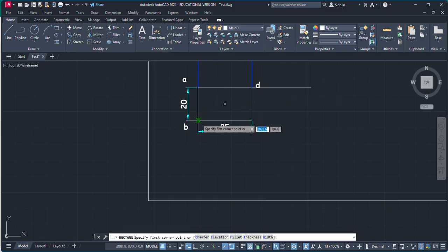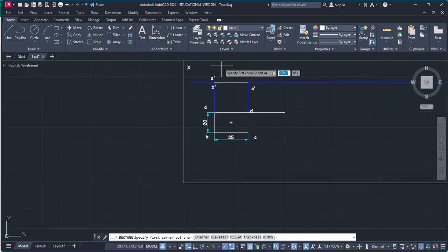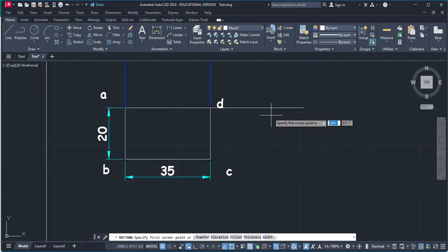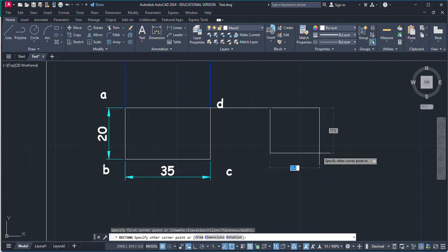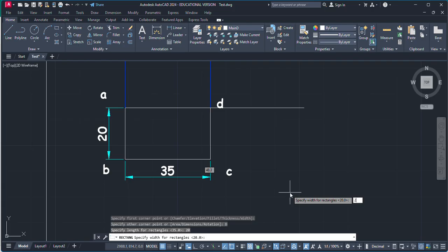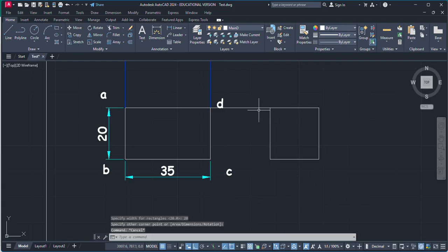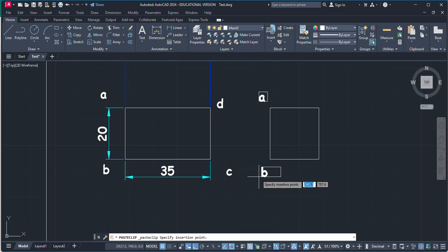So this is the resting edge, so this is not going to change. When we incline the surface with the HP, this length gets compressed and this length will become 20, because in the top view we will have a square. So this is the resting edge, there's not going to be any change in this edge. So just make a square from here. Dimension will be 20 by 20. This is given, because these are the given things for the second condition.